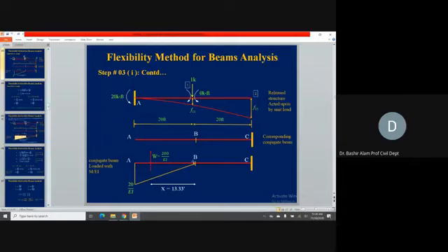And we can find out the distance also. From this less load intensity, 0 load intensity, the moment arm will be 2/3 of this horizontal distance. So 2/3 of this 20, which is 13.33. So 200 times 13.33, that will become our F11. And F21 will become equal to 200 divided by EI times 13.33 plus this distance, which is 20 feet. So that will give us F21.